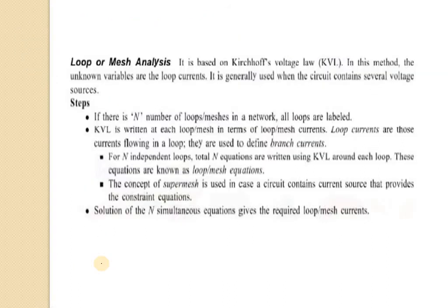Okay. Now, next one is loop or mesh analysis. It is basically based on Kirchhoff's voltage law, KVL. In this method, the unknown variables are loop currents. It is generally used when the circuit contains several voltage sources.